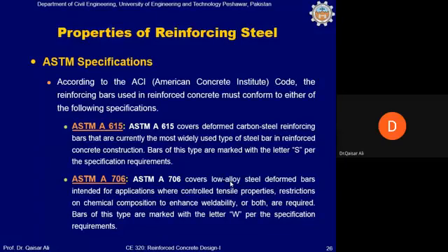You will be able to see that steel strength is achieved by adding carbon to the iron, but it has a limit. The carbon addition has a limit. After that, if you add more carbon, then although the strength may be achieved, the ductility will be lost, and we, as engineers, would like our steel bars to have strength and ductility both.